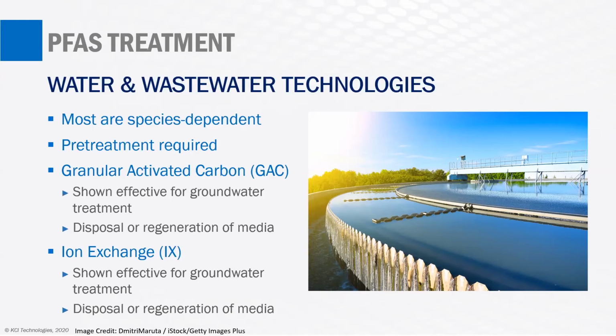These are a couple of the front runner technologies for PFAS removal, and they have been shown to be effective in groundwater treatment. But there are a couple of things we've got to deal with, and it's going to affect almost any of the technologies we're talking about on the water side. And that is, you've got media that gets exhausted and has to be either disposed of or regenerated. If we're moving our PFAS from the water to a granular activated carbon particle, and those are being taken out and disposed somewhere, it may be more stable there than in the water, but what's our long-term impact of that? To some degree, we don't know.